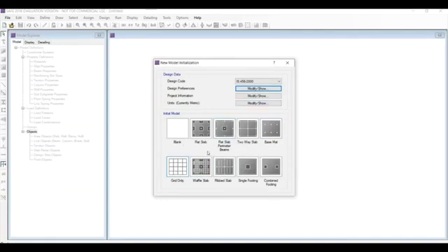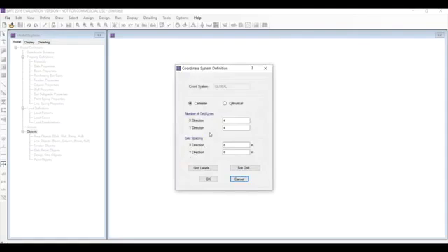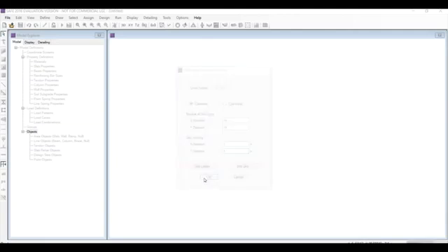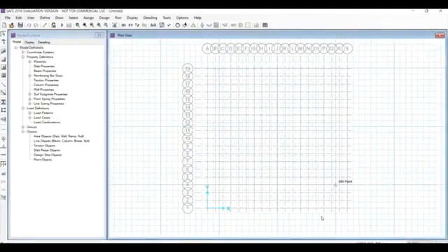And now go for grid only, as we don't have a mat foundation prescribed format, we have only base mat, so let's go for a grid only system so that we can have our own dimensions and our own columns. For an 18 by 18 meter mat foundation, we need at least 19 grid lines, if we take each 1 meter as one interval spacing of the grid line. So take x direction 1 meter spacing and y direction 1 meter spacing and click OK. Now we have the grid lines of our mat foundation.